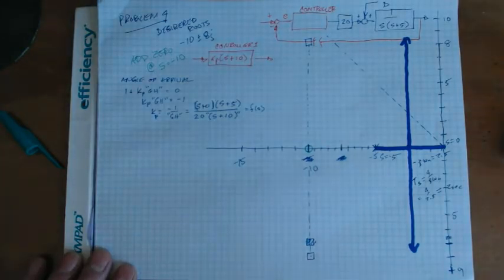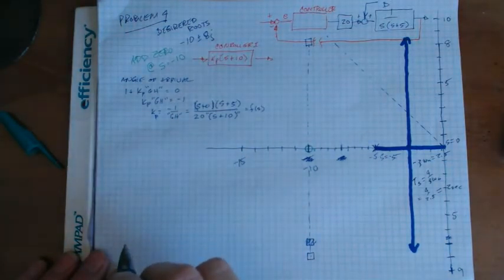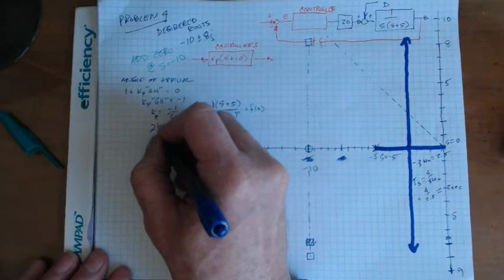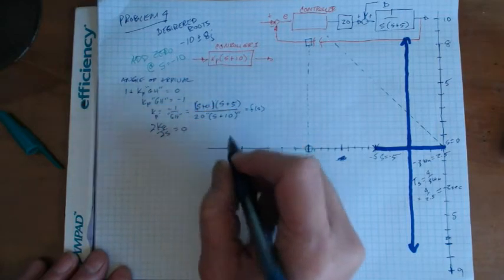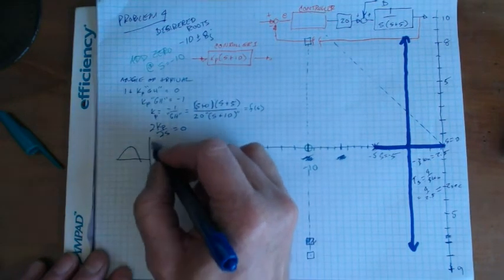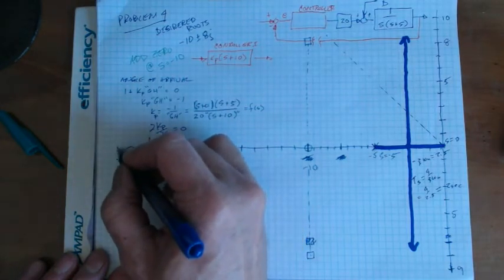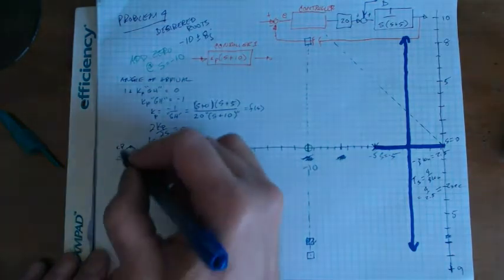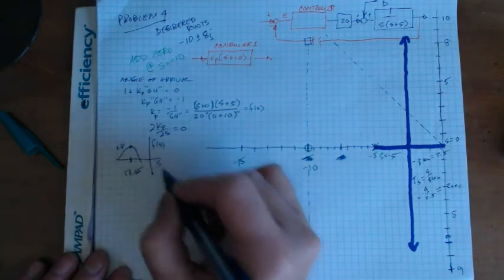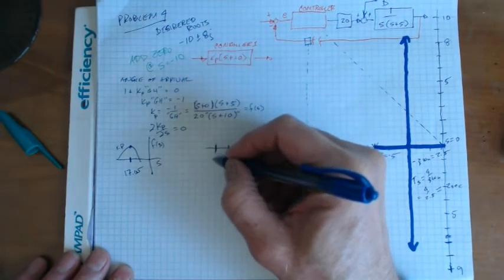Okay, if you go back and look at the last problem, this is going to tell me that for f of s, when I take the derivative of Kp with respect to s equal to 0, I can either just plot this. Here this is f of s, this is s, and this is Kp here, and I just look for the maximum value, and it turns out that maximum value is 17.05. If we try it out, 15, 16, 17.